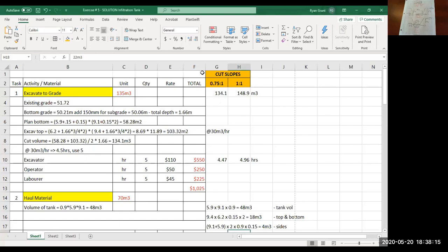Okay, so on the assignment, the wording was a little bit tricky. I mentioned the quality of the excavated material was, I forget the exact wording, but the intention was that the type of excavation that you were in, the ground was pretty good. So according to WCB, you could be steeper than 1-to-1. According to the PowerPoint presentation that we looked at during week 5, you could be as steep as 3/4 to 1, which is steeper than 1-to-1.